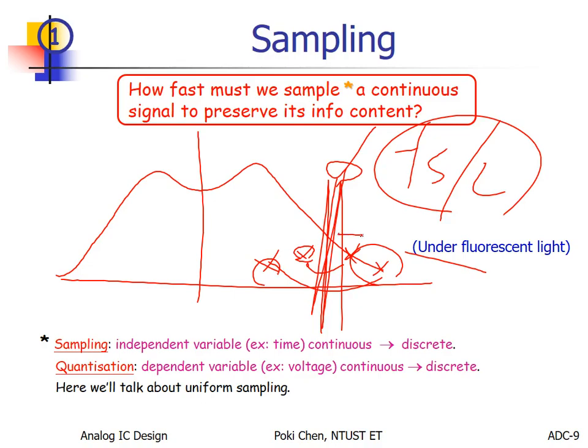If you go even further, even beyond the sampling rate, it will fold back to your medium band to low frequency band all the way.